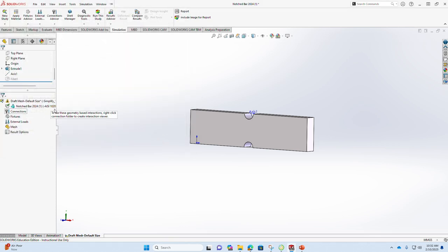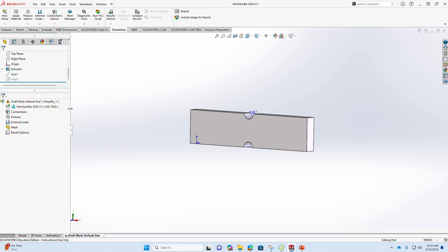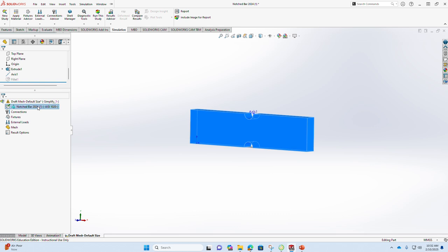You can see here, where the name of the part is given, in front of it is now the name of the material that you have chosen. Okay. So now that means your material has been assigned. If this name does not show for whatever reason, it means you need to redo the definition, and you will need to reassign the definition. Okay. So that's the first main step.